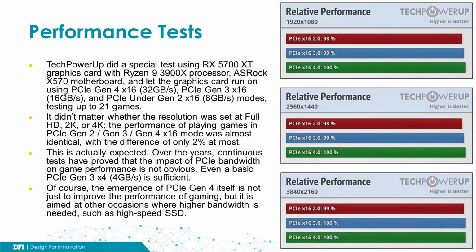Over the years, continuous tests have proved that the impact of PCIe bandwidth on game performance is not oversized. Even a basic PCIe Gen 3 x4 is sufficient. Of course, the emergence of PCIe Gen 4 is not just to improve gaming performance, but is aimed at other occasions where higher bandwidth is needed, such as high-speed SSDs.